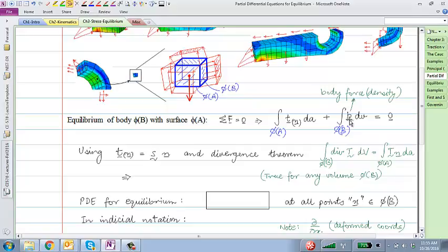That weight is obtained by taking the volume of the body, multiplying it with the density to get the total mass of the body, and mass times gravity is the total weight. So weight is a type of body force, but again, we can't say that the body force is a point load acting at the center of gravity. That point load is the resultant force from all of these small body forces acting on the body. So this B is a body force density.